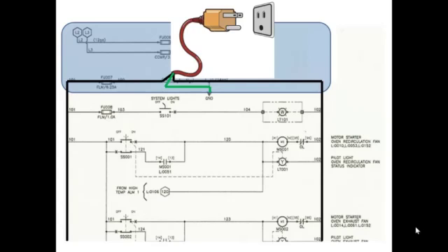and if you scan down through it, you'll see that there are electrical conductors that go from left to right through fuses, switches, and lights, switches and lights, relay coils, etc. So what you're looking at right now is actually 3 separate circuits that all share this power source.